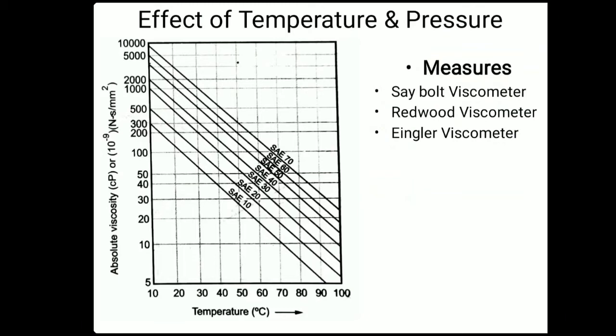Generally for a two-wheeler, we do servicing every 2000 kilometers. So what is servicing? Servicing means changing of the oil. Why? Because with usage of that oil, due to the temperature during the working condition, the viscosity of the lubricating oil is reduced. The total lubricating oil, while being removed, is black in color.